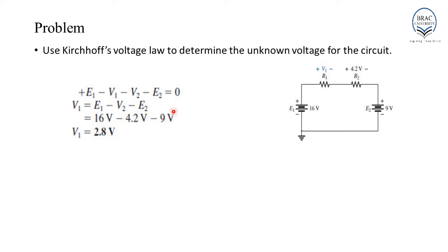Now, if we substitute the values of E1, E2 and V2 in the equation, we can easily determine V1, which is 2.8 volt in this case.